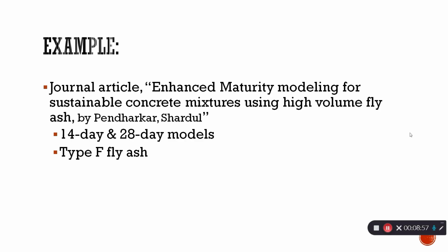There were 3 approaches taken to calculate activation energy and prediction models made on these approaches. In the first approach, the limiting strength of each mixture at different curing temperatures was considered. In the second approach, the setting time of each mixture was considered. In the third approach, the limiting strength was kept constant for each mixture regardless of curing temperatures.